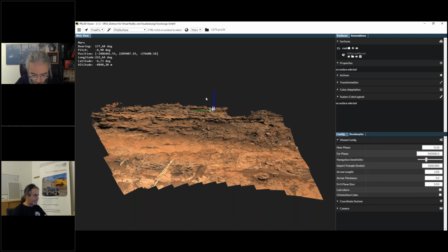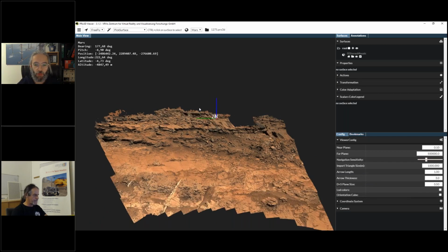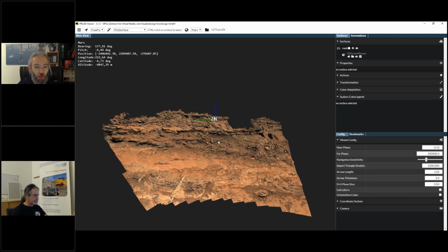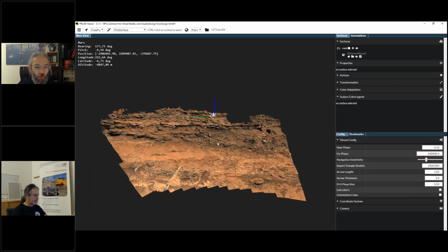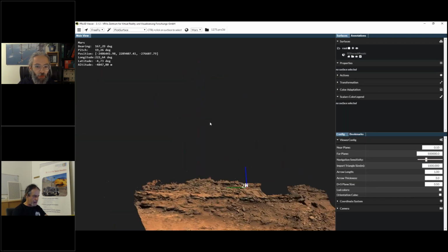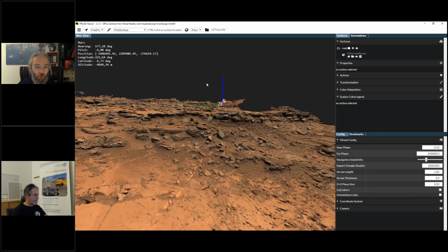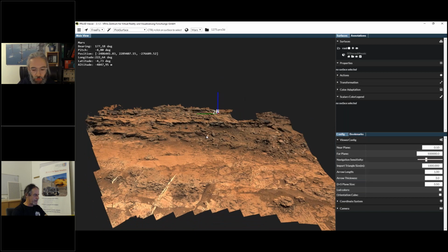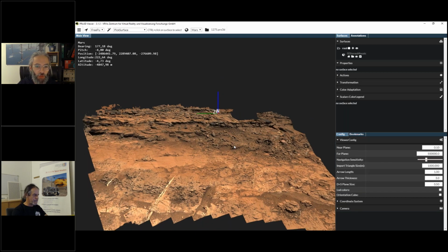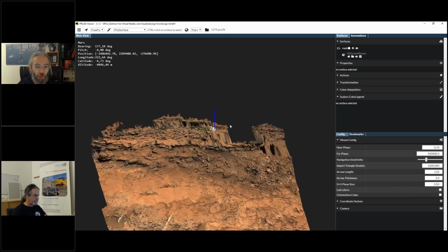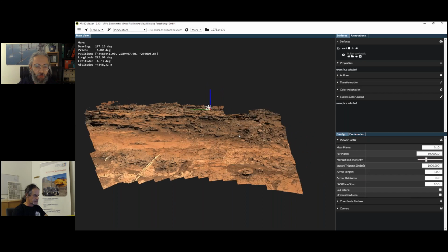As a next step, I will give you some introduction about navigation. I've already been doing this so far. This is the free-fly navigation. You can steer with the mouse. The left mouse button changes the orientation. The right mouse button goes closer and further away when moving your mouse. And the mouse wheel does the same. And the middle mouse button allows you to pan in this free fly navigation.